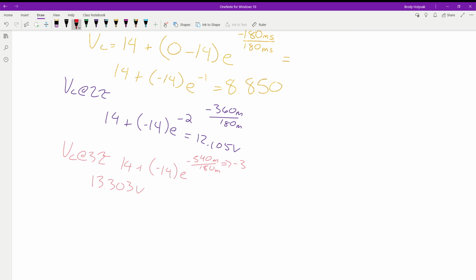Okay, here's a trick question. We're going to work it backwards. Since we have this pattern, what voltage would we expect just based on this value, our 98.2? How would we find that? Yeah, 14 times 0.982. We could also find this by plugging in that formula with the exponent changing to -4. So the taus are really easy to find if we can remember these percentages.